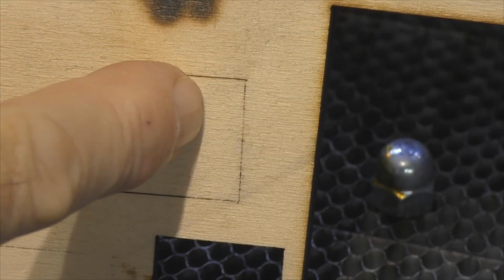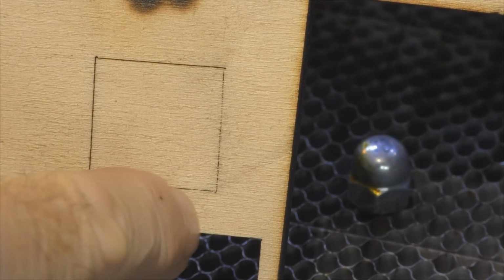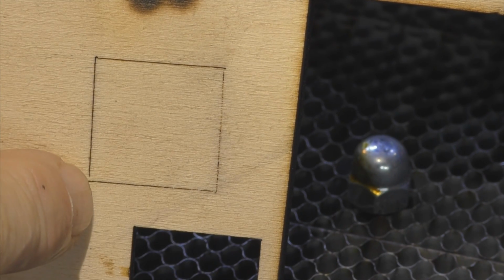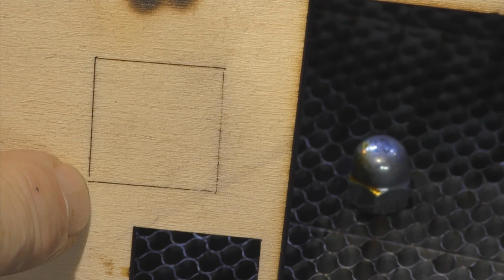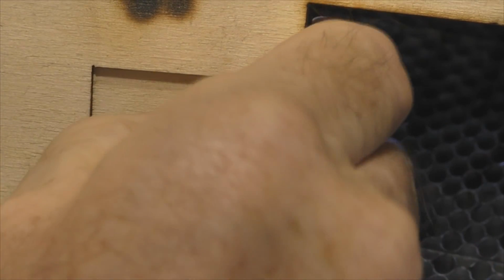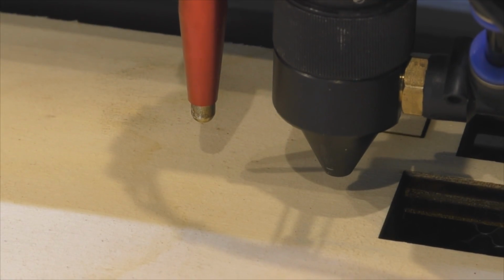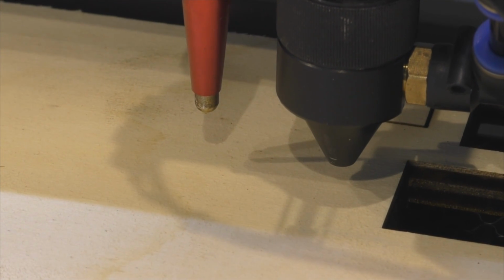If we look closely here, you'll see that it hasn't really cut through, and it certainly hasn't done it on the corners. You can see where the corners have dragged. You can see these little bits that are missing here, look. But that's not a cut. That's a struggle. So I think we found the optimum at 10 millimeters a second. That was a bit of a lucky guess. So let's see what other factors we can change to maybe improve that 10 millimeters a second.